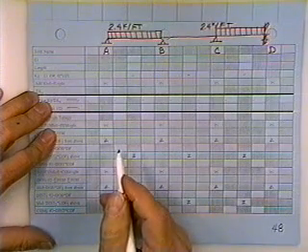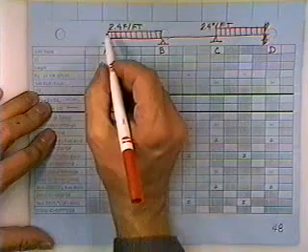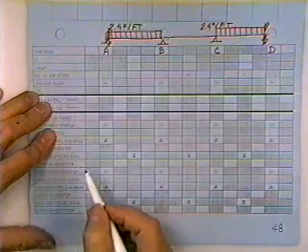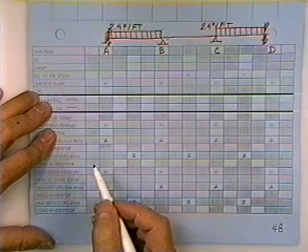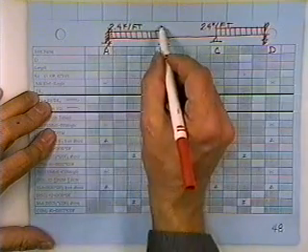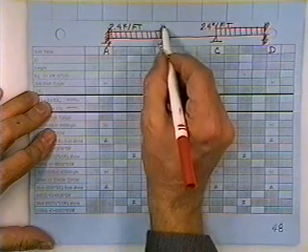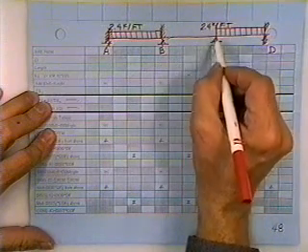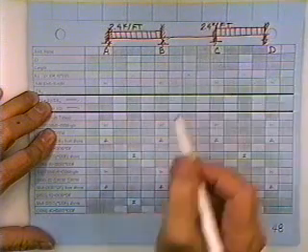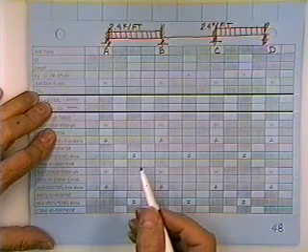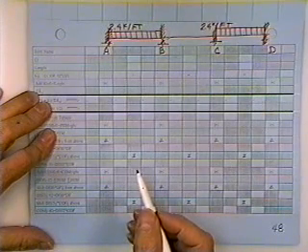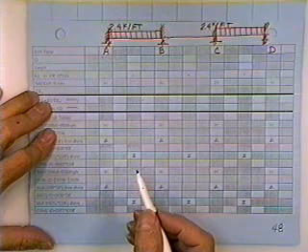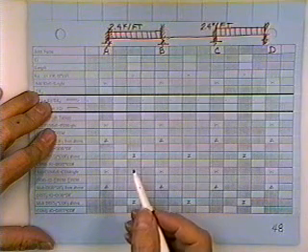So what we do with the structure is we lie. We come to joint A and we pretend there's a guy with a wrench who does not let joint A rotate. We put a wall at joint A. We come to joint B and we do not let that rotate. We put a wall at joint B. We come to joint C and we put a wall. And we don't have to lie at D, there's already a wall at D. Now then, the structure is not loose to do what it would like to do, but at least it does something I understand.